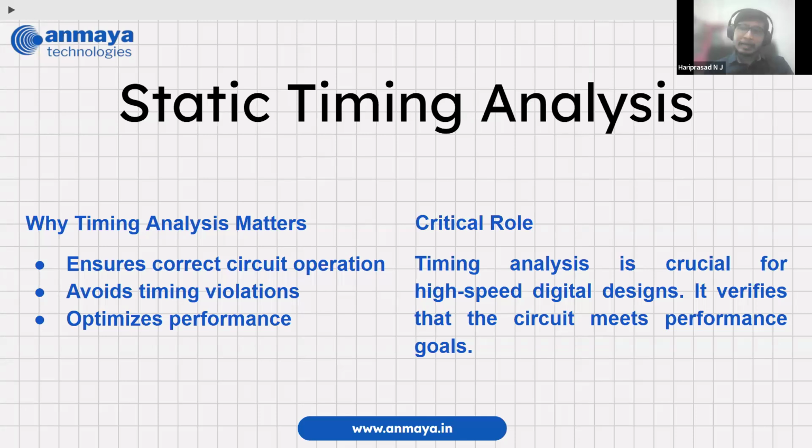By changing my clock frequency to 100 megahertz, definitely this setup violation will go, but that purpose is not served, because I reduced the performance. I have to keep the 200 megahertz as is. In the architecture, I have to modify things in such a way that this setup violation is resolved. That is my objective. How we do it, we have to understand.